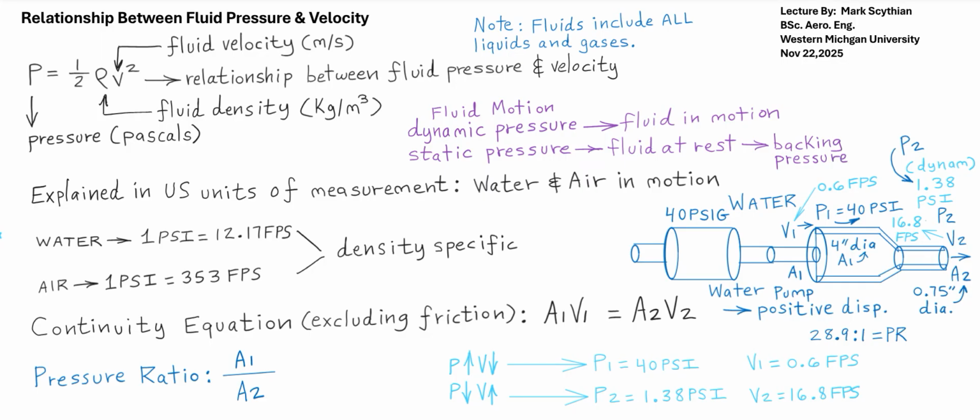So if you had a pressure gauge, static and dynamic on the gallon of water, before opening it up, the dynamic pressure would be 0, static pressure would be maximum, and then you open up the cap and you'll see the static pressure suddenly drop, but not go to 0. It'll be a little bit there, but then the dynamic pressure will be surging until it stabilizes. So we could also describe static pressure as backing pressure, but the pressure incurred during motion is the dynamic pressure.